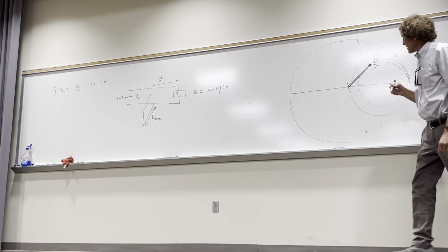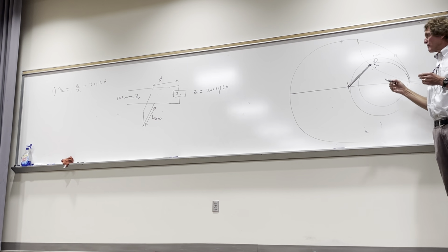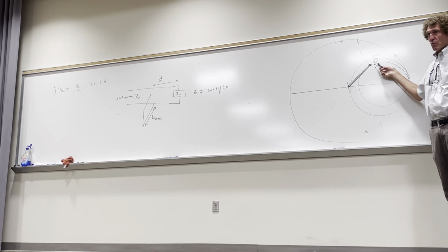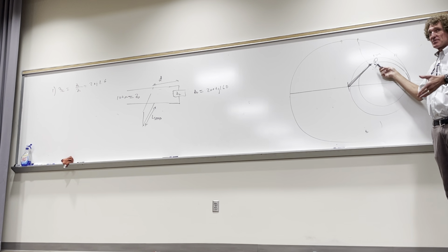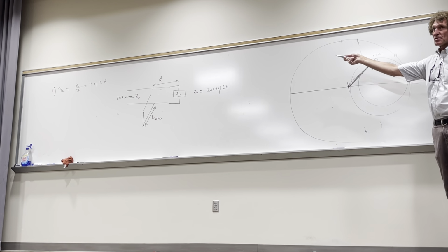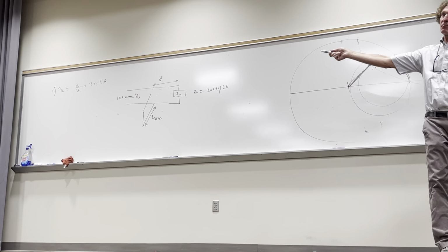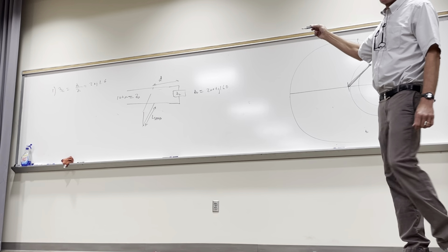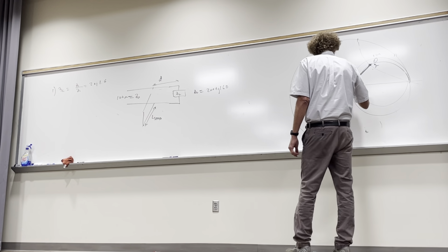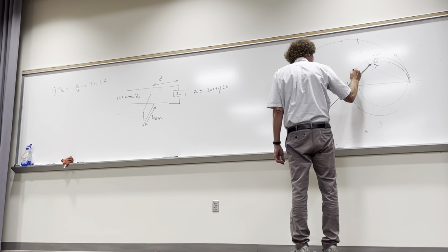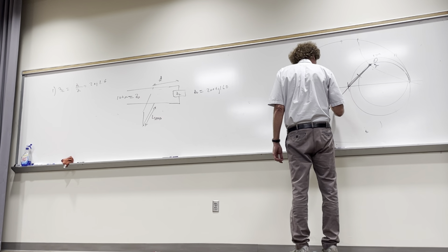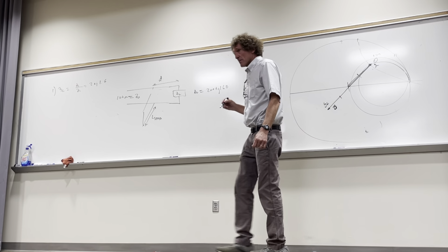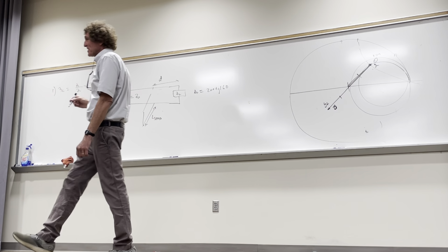That's what I'd like to see on the final exam, where you label the point you enter as 1. The next point you go to would be 2. Now this is going to be a shunt stub, so we're not going to work in ZL, are we? We're going to work in Y, right? How do we get that? 1 over that, we just draw a line, and this would be point 2, which is YL, okay?